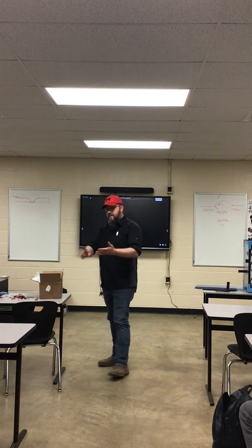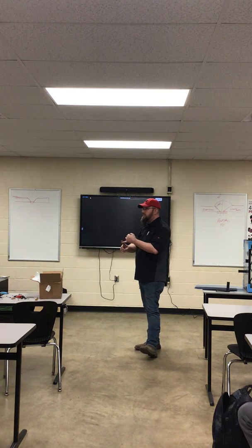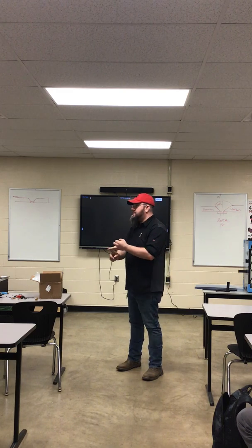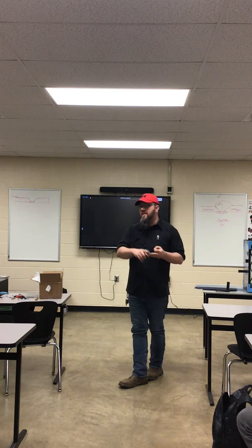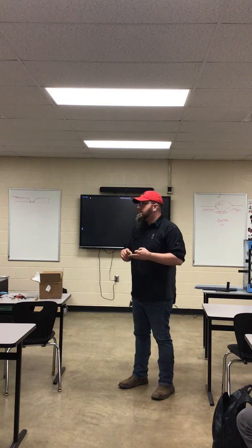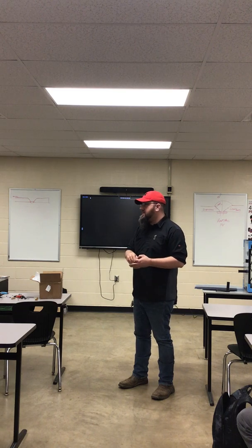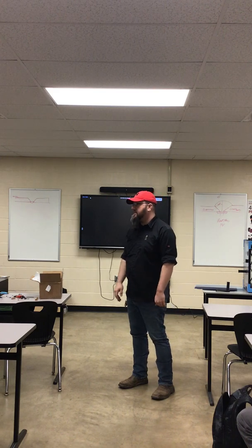You're gonna take trimmings of your original material, right? You're gonna follow your WPS, right? You're gonna go through all the steps that have to be done, following interpass temperatures, all the pre-process, post-processing steps that are required. You're gonna send that specimen out. You're not gonna go cut apart a finished object, right?